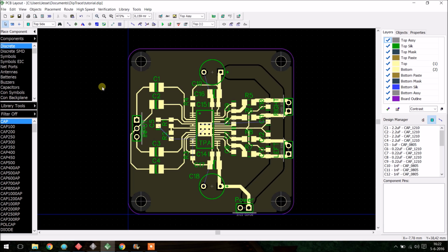In the next chapter I'll tell you how to 3D preview your board so you can check for visual errors. If there aren't any, you can go on to the next step, which is outputting to a Gerber file, so you have a file that you can send to the board house, then they can produce your board. Since our board is only 50 by 50 millimeters, we could even make it smaller if we want. But since it's so small, you can go to Seeed Studio or iTead or another Chinese PCB manufacturer. You can get 10 made for $10, which is a great deal. And they'll ship it to your house in about a couple of weeks, maybe a couple of months, depends on the time of the year.